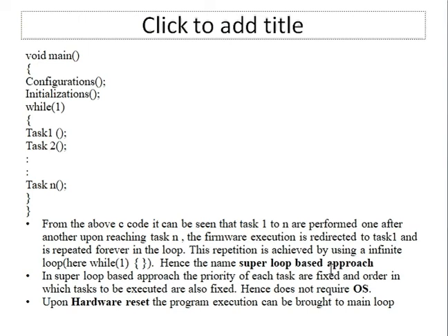Here you are not using an operating system. One of the disadvantages of this method, already addressed, happens to be when there are multiple interrupts connected to the embedded product, which interrupt you need to give the highest priority is not defined, and it is difficult. And also when you expect the response time from the microcontroller unit to your interrupt to be very fast, then you cannot afford to use a super loop based approach. A super loop based approach cannot be used as firmware for developing applications under real-time scenarios.